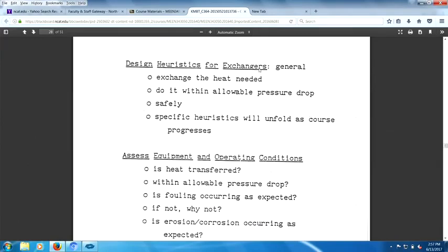The other thing I want to point out is allowable pressure drop. See the allowable pressure drop? That's not really what it says. It says utility bill. It takes power to run a heat exchanger. So I have pressure drop times volumetric flow rate. Very fundamental equation you should have learned in fluid mechanics. Again, flow rate times pressure drop equals power.